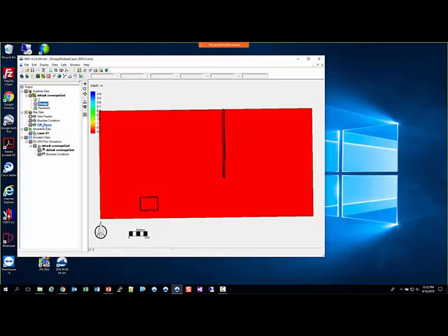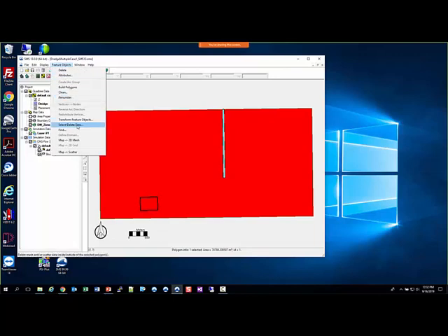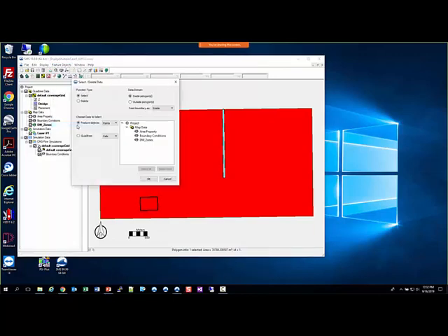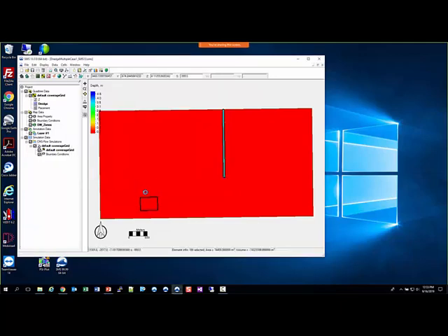So now what we can do is, for each one of these zones, select the cells inside of there and then modify these values. So let's work on the dredge. We will come over to our map module, select that polygon, and then under feature objects, there is a select delete data. We can make sure we select inside the polygon for the quad tree. There's only cells available, and then we select the actual quad tree grid that we're working on and say OK.